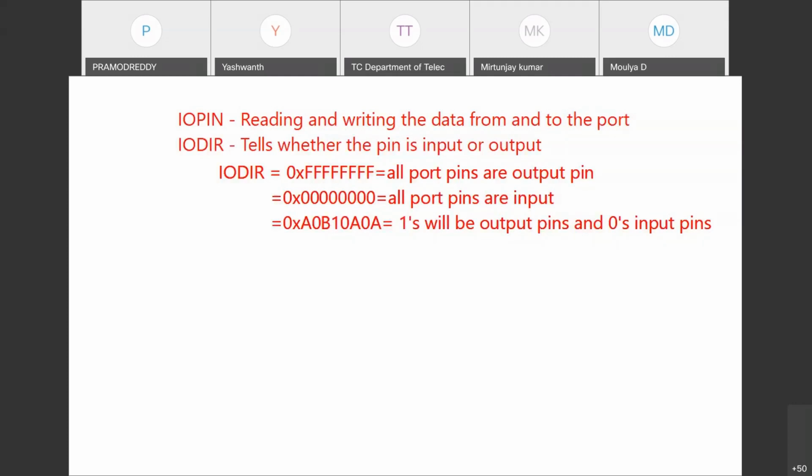There are various methods. How to assign the value to a register? If you take an example, IODIR = 1 << 3. It means I'll put the data 1 into IODIR, shifted left by 3. So the meaning is P0.3, if I call it IODIR0.